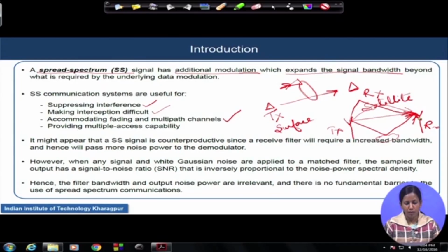And because of this multipath channel concept and the fading, which is basically the attenuation in the amplitude and change in the phase of the transmitted signal with which you receive the signal at the receiver, with that whole concept of fading and multipath channels, your received signal needs to be clarified, needs to be cleaned up before the demodulation and detection process proceeds in the receiver circuit.